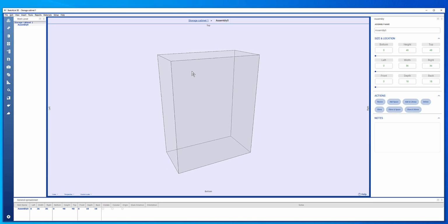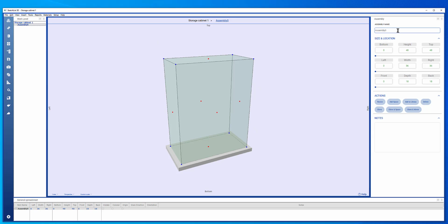SketchList creates the project and inserts the first default cabinet, which we are calling Main. By default, the newly inserted assemblies have the same size as the project. The design process largely involves two steps using three tools. First step is to insert a sized board. The second step is to locate the board within the design.